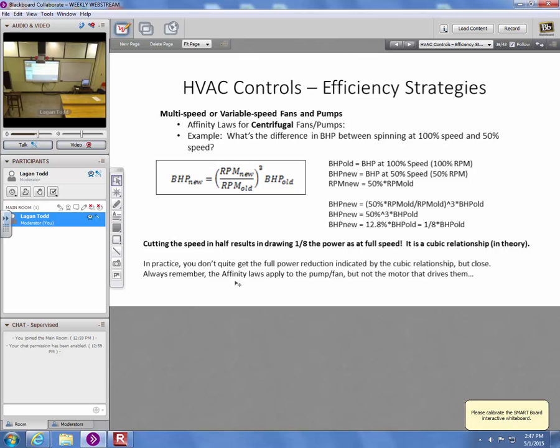This is where the variable frequency drive comes in as a really important part of this whole puzzle, because if you change your motor speed, you don't get that same severe drop in motor efficiency. You get a little bit, but not anywhere near. I've seen 70% loaded motors that are running at about 60% of their peak efficiency. It takes a pretty sharp dive when you get down below about 70% load.